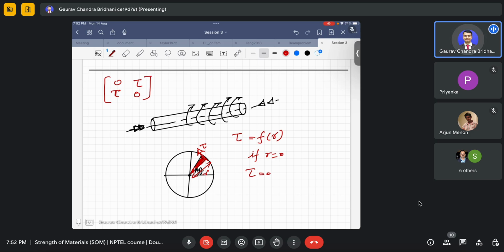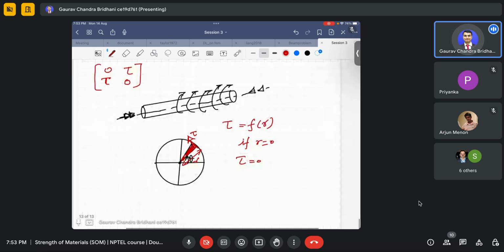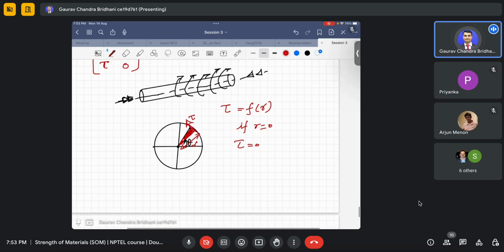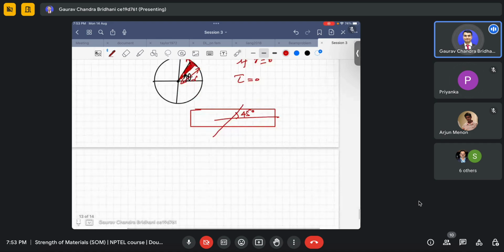Okay. So now the question is how the chalk got failed at a different angle, because in the case of pure shear or in the torsion case, the chalk fails somewhat like this, at 45. It fails either in this plane or in this way, if the type of rotation varies. So it will be from this axis 135. It depends whether you are rotating it clockwise or in the other sense, anti-clockwise.